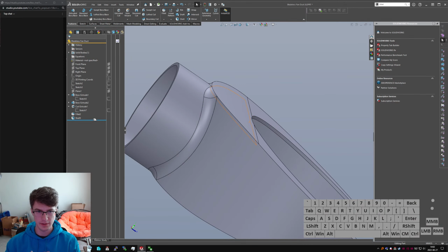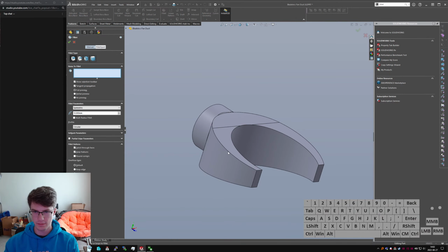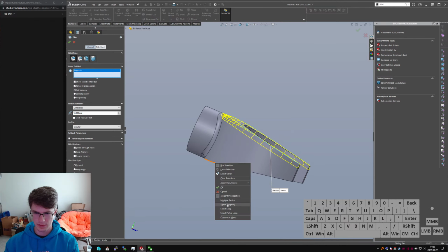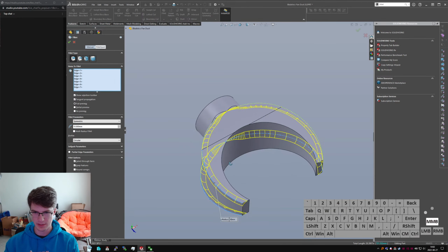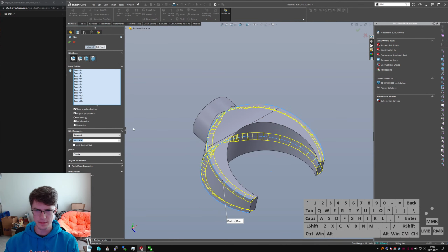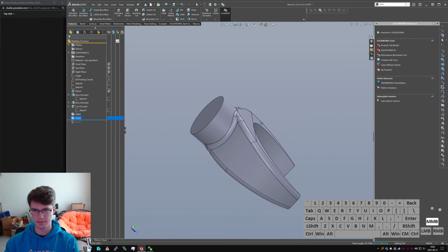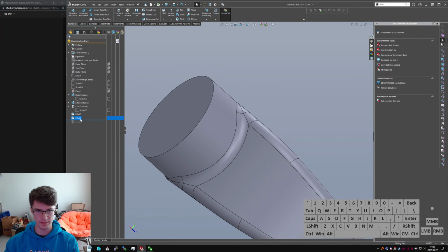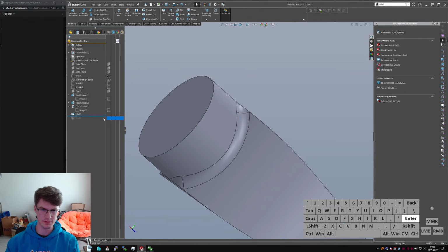Looks a little unrefined though around the edge, so we will add another quick fillet, and I think maybe the quick options will give me a nice... No, not any nice ones that are going to pick just the edges I want, so we'll have to select tangency to make sure we get the edges we care about. And that'll also tell us if things break. Like it'll throw alarm bells up. Ooh, and if I put... Oh, I see. I've done these in the wrong order.